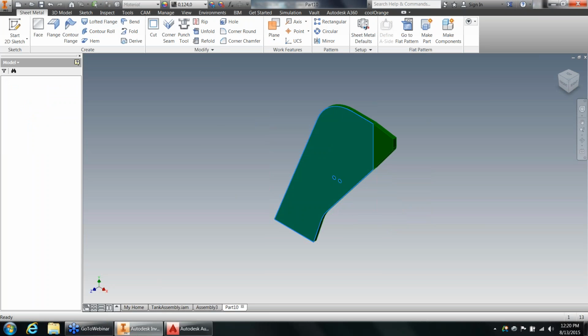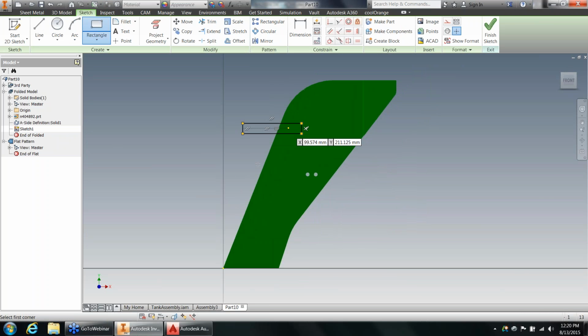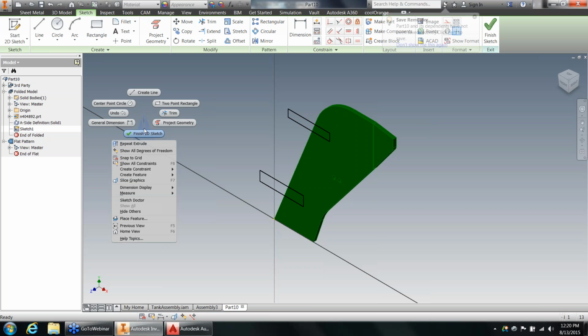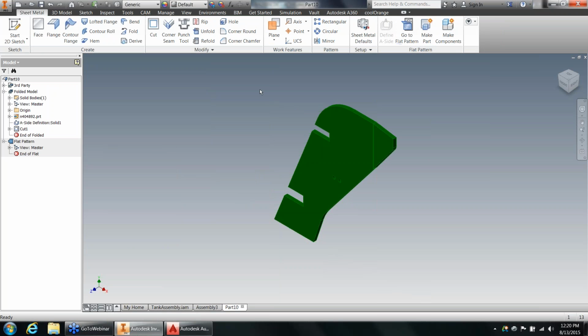Beyond that, because it's a functional solid, I can come in and perform operations on this part as well, making adjustments on it as necessary. And then in this case, we'll just use our sheet metal cut tool to cut through that thickness apart and update that solid. So it really just allows me to flush out an existing solid part without having to break the association or the associative link to that data.